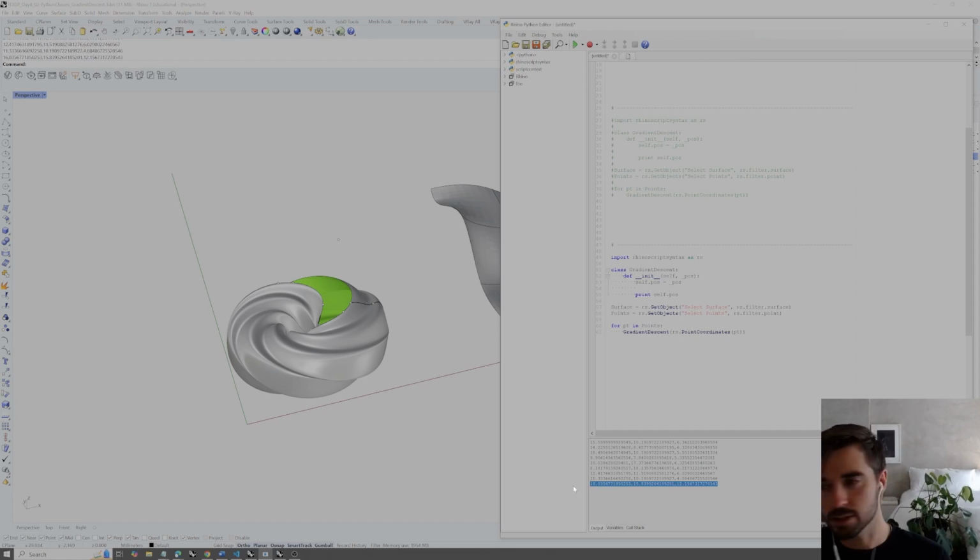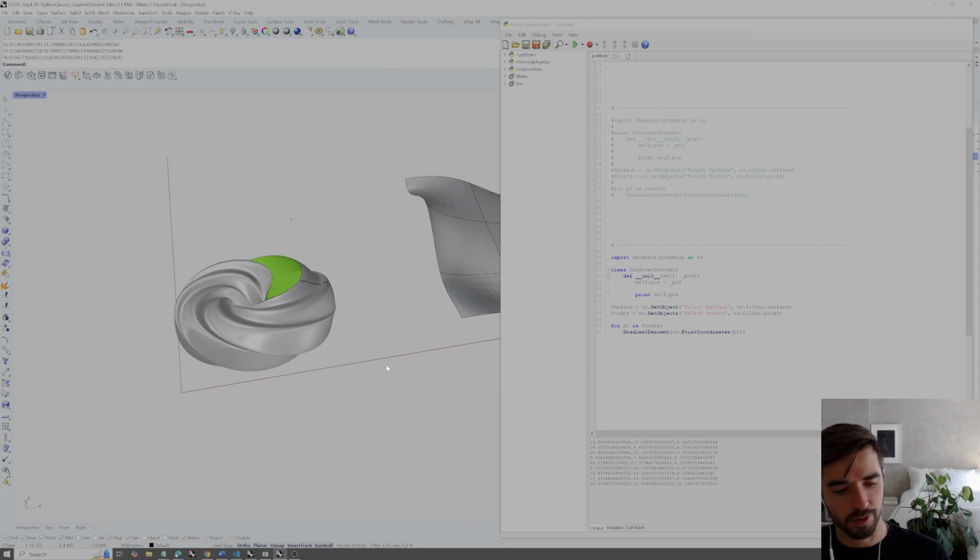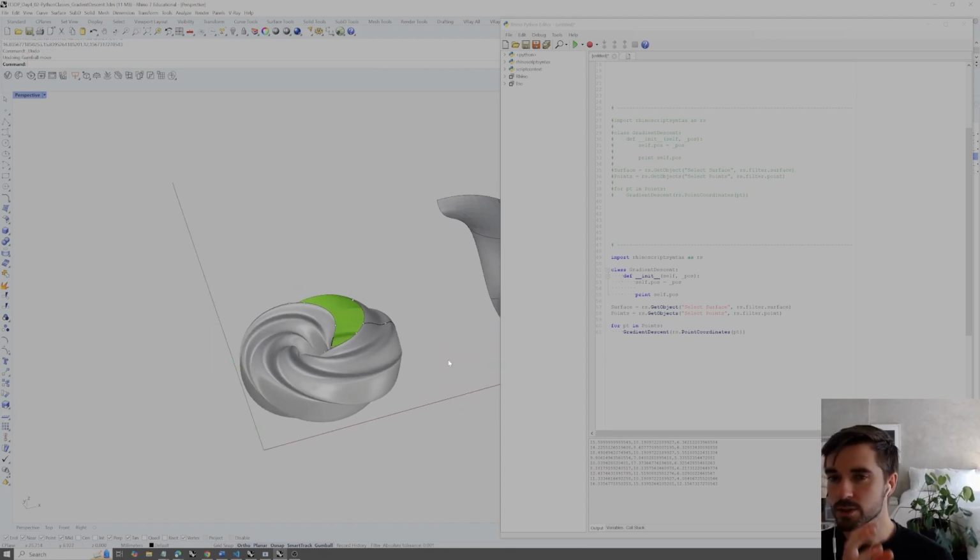We could lift this point up, hit play, select our surface and then our points, and it's going to still consider that one of our points, which is at 12 units in the Z. So it's off the surface in the Z. So we want to snap that back down to values or closest values on our actual surface. Well, how can we do that?